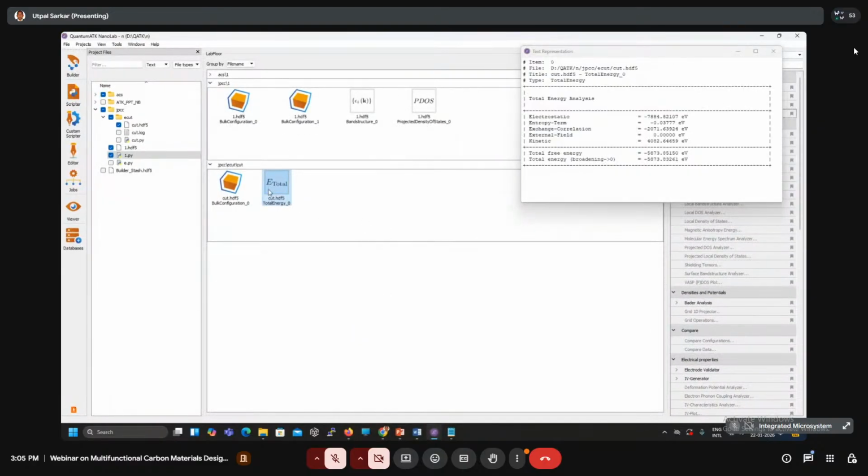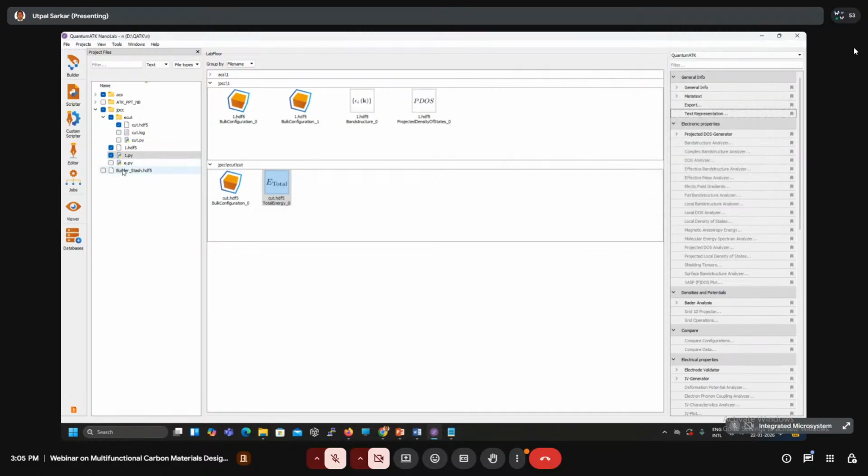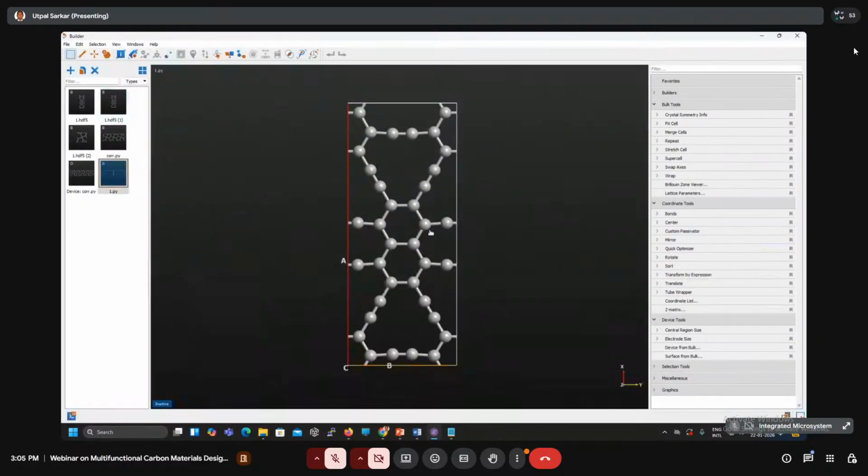So as you can see, for the k-point sampling also you can see the total energy. So for k-point sampling also you have to monitor the total energy, and you have to take care of the saturation up to 3rd decimal point, so that the change in energy will be negligible. Then we can take that k-point sampling for the optimization. Now I am going for the optimization part.